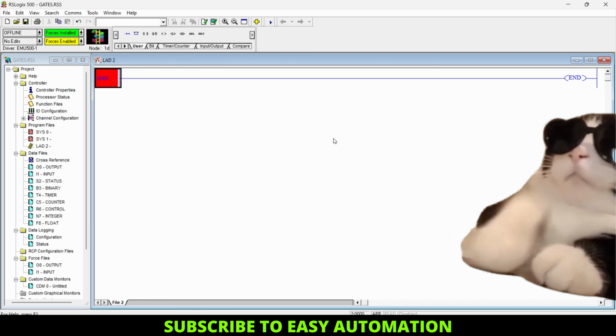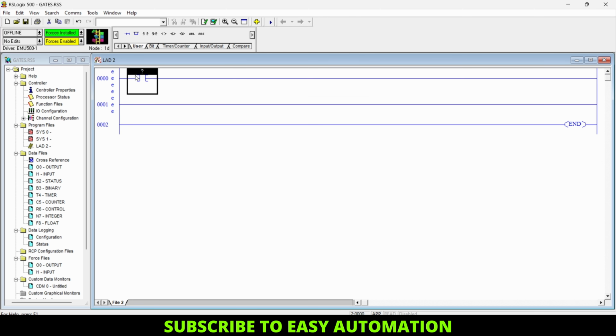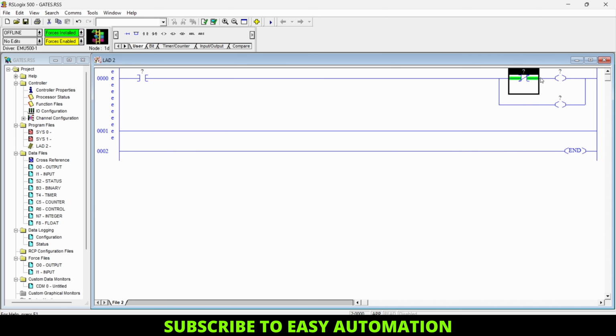For creating this program, we need two rungs. I will add two rungs here, and I will add one NO contact and one output coil, and one branch instruction. I will put this output coil in the branch instruction, and add one NC contact with our output coil. This arrangement can give us the triggering pulse which will be used for turning the output off and on.